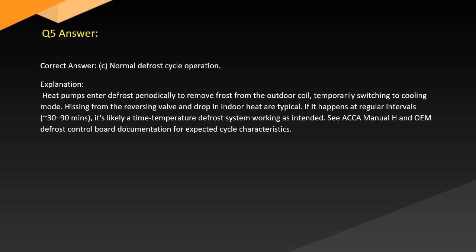Answer. Correct answer, C. Normal defrost cycle operation. Explanation. Heat pumps enter defrost periodically to remove frost from the outdoor coil, temporarily switching to cooling mode. Hissing from the reversing valve and a drop in indoor heat are typical if it happens at regular intervals. 30 to 90 minutes is likely the time temperature defrost system working as intended. See ACCA Manual H and the OEM defrost control board document for expected cycle characteristics.